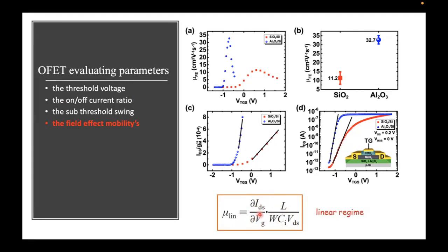Now, as you see from the previous equation, even from this equation you see in this slide, the capacitance of a transistor, or what we can call between brackets the parasitic capacitance of a transistor, is a very key parameter in design. And you can understand that this capacitance can differ whenever we change the topology or the architecture of the transistor.